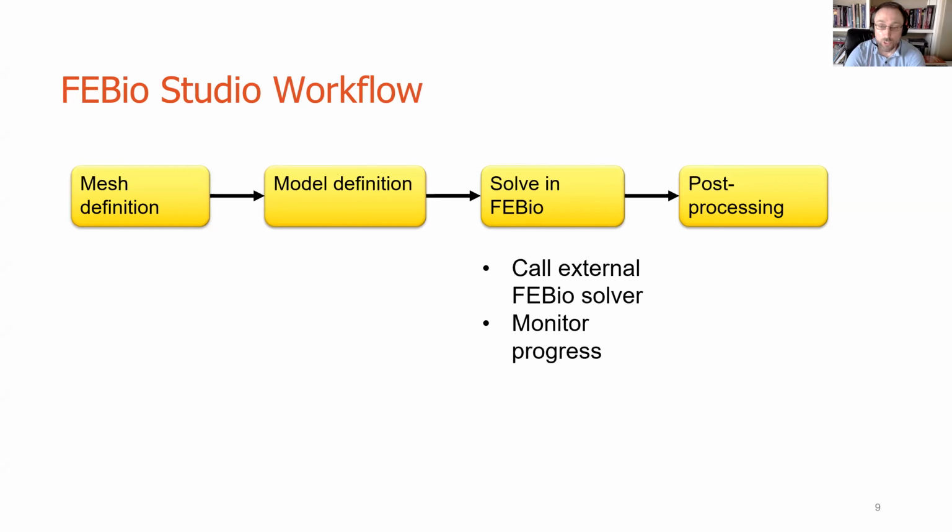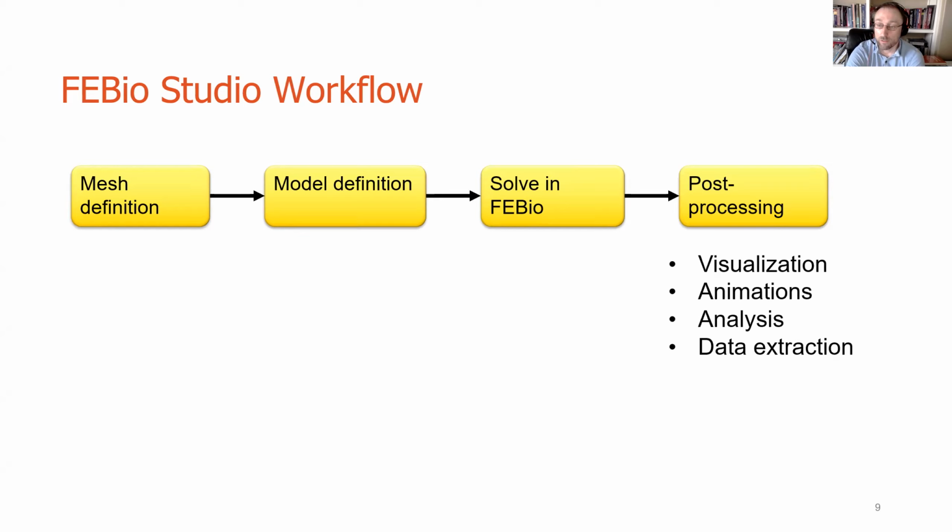Then you would solve this in FEBio. As I mentioned, FEBio is an external package, but you can run it from within FEBio Studio. So you don't have to leave FEBio Studio in order to run FEBio, although you can, and I will talk about that later, how you could do that, run FEBio from the command line, that is. But once everything is done, you can bring the results back into FEBio Studio, where you can do visualization, animation, analysis, and data extraction. So what we're basically going to do is we're going through this workflow in this order.